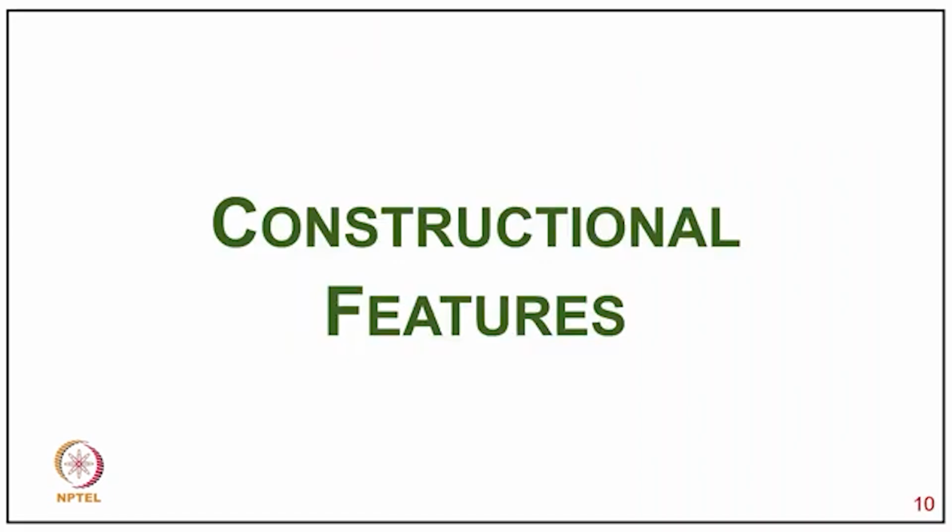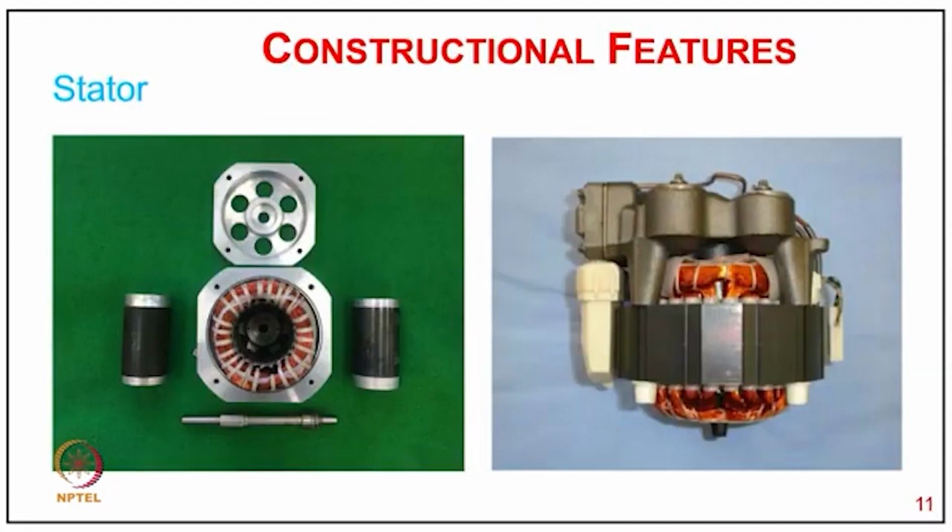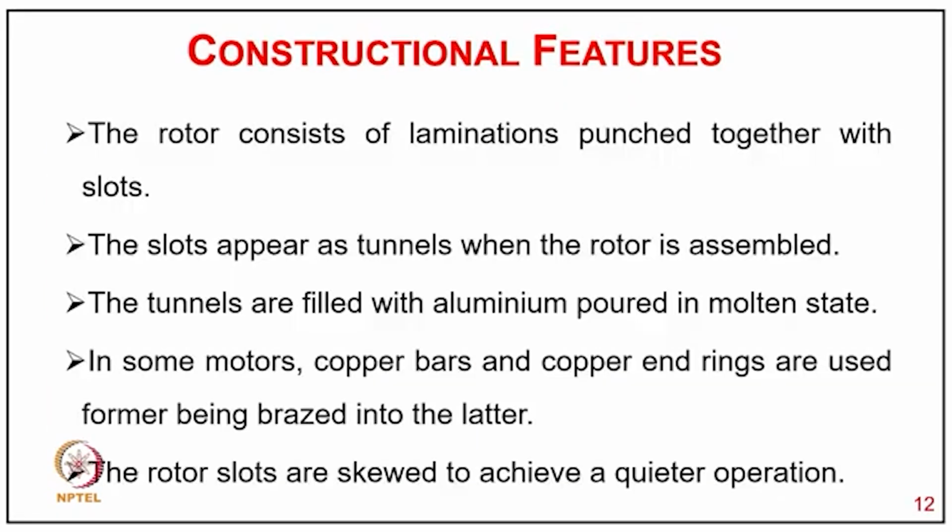Now coming to constructional features of the single phase induction motor, as you can see in the photograph, we have normally a squirrel cage rotor, then a wound field stator, along with the other accessories, typically the capacitors, which may be for starting or running, and of course the shaft.